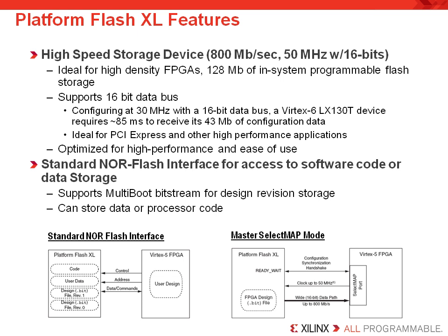The XL also has a power-on-burst read mode and dedicated I/O power supply, which enables the Platform Flash XL to mate seamlessly with the native SelectMAP configuration interface.